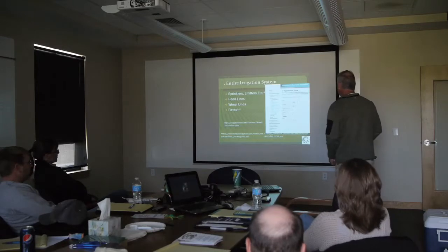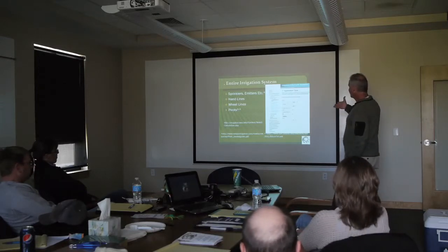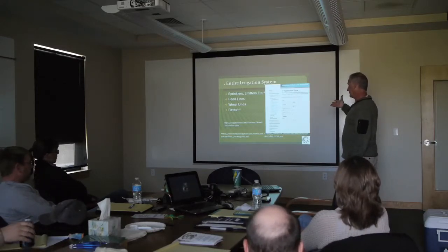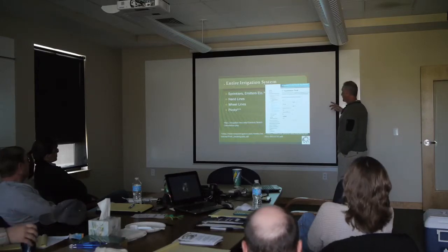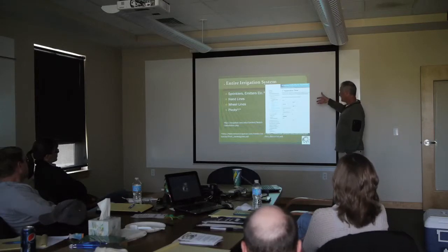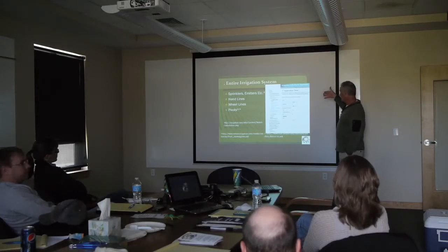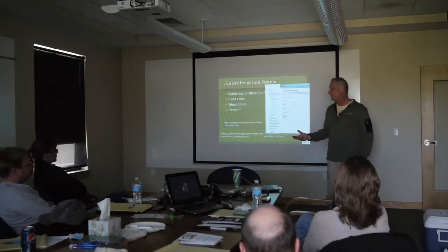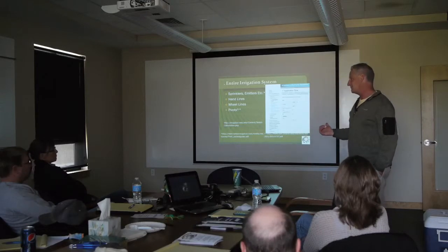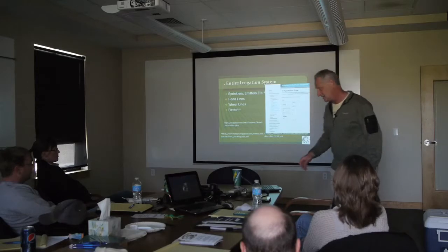Let's see, this is another online calculator that I thought was pretty good, where you could put in the size of the field, timer settings, how much of the circle, field efficiency, and it'll calculate how many GPM you need. Okay, so that's just awesome, saves you a ton of time to figure that stuff out.